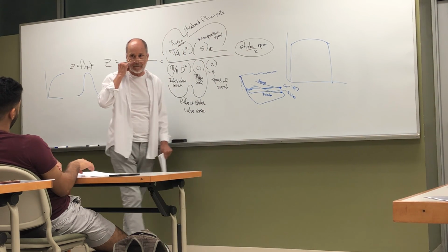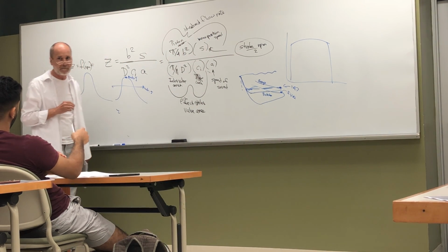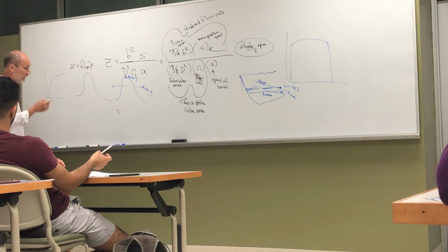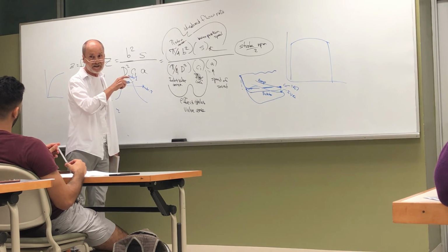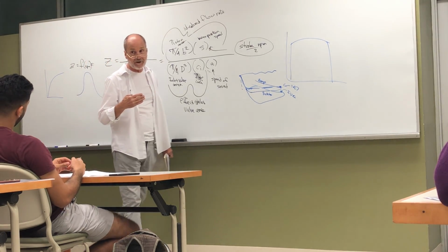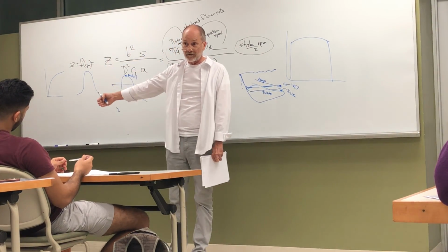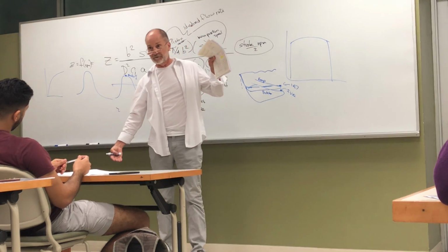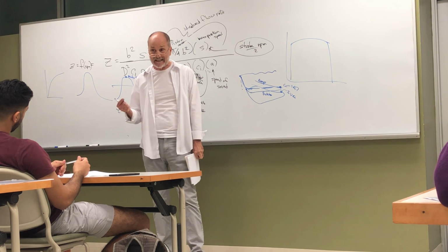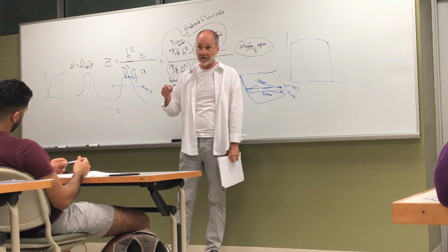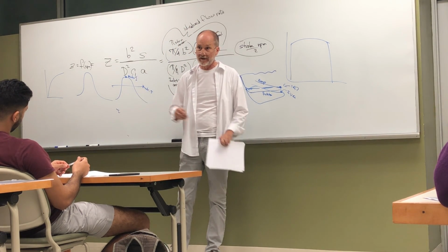The Mach index means the velocity of the intake gases, right? Well, if you're flowing faster, idealized, to get it to move faster, if the gases move twice as fast, we have to have 4 times the pressure differential because it's turbulent flow. And the pressure drop needed to support the higher velocity is a function of the velocity squared.